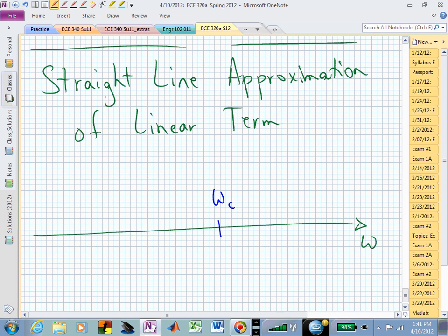Let's say we had a pole at 2, then we would locate that. If this is 10 to the 0, 10 to the 1, 10 squared, 10 to the minus 1, then this would be omega equal 2. That's supposed to be 30% of the way or distance between 1 and 10. Is that making sense? We locate that, and now what happens?